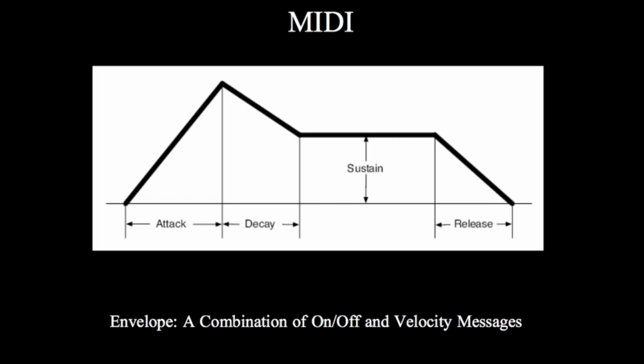I could also get a sense of how far the key is pushed down, but really the mechanisms on these electronic keyboards... if you were to have a mechanism that could really just measure how far the key had been pushed down, it would be very fragile. However, they were able to develop a much stronger, sturdier technology that could measure how fast the key went down. So the speed of the key going down, of course, correlates to how loud the note is on a piano.